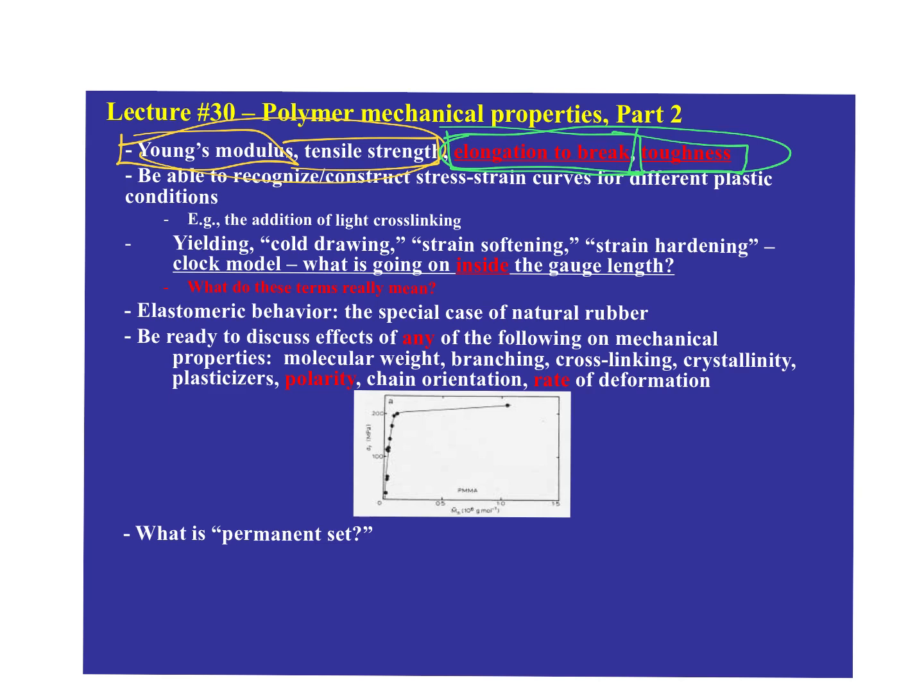And so this is something that I still see on the tests where, I can have a high modulus and a really low toughness. All right, so don't tell me the mechanical properties are improved, because I'm confused, because toughness is a mechanical property, Young's modulus is a mechanical property. I know they don't both improve at the same time. All right, so this is why you can't be generic about saying mechanical properties. Or you say what property you are talking about. Young's modulus, or you're talking about toughness. So make sure that you are aware of the fact that these can go in very different directions. It's very difficult to improve both of those things at the same time. Okay?